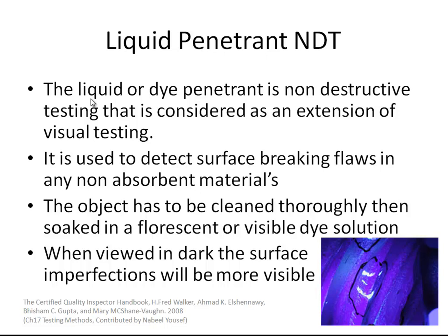So it is used to detect surface breaking flaws in any non-absorbent materials. We don't want the material to absorb the dye or the liquid that we are using, and the object has to be cleaned thoroughly, then soaked in a fluorescent or visible dye solution.